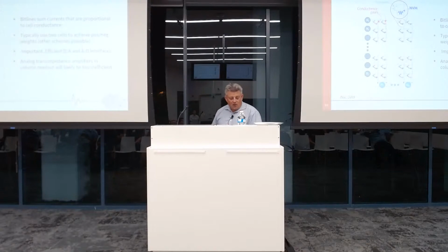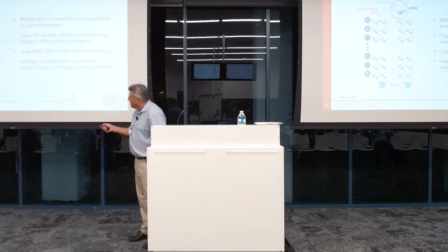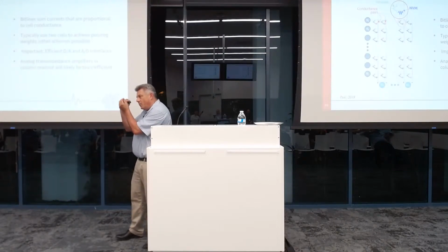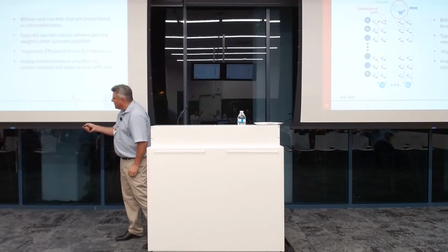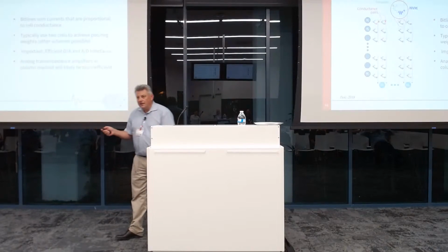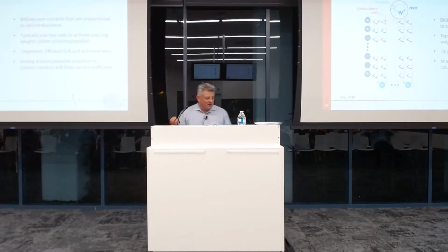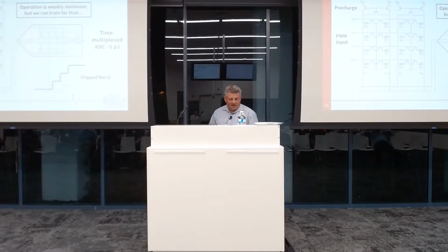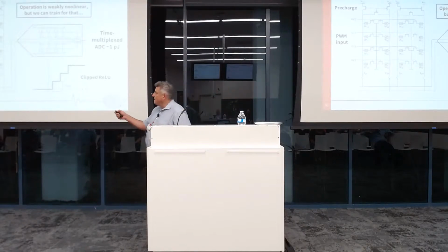So it's now all about, right? So remember, if my tile is very efficient and my energy is very low, and this is all very dense, very low capacitance, the only way I could ruin this then is by attaching inefficient circuitry at the periphery. And this is really where you have to watch things. So this is precisely what we are working on in my group right now. We're working on efficient digitization of these column-wise computations.